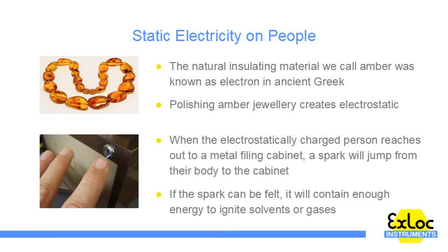If the spark is large enough to be felt or even hurt, it will contain more than enough energy to ignite most solvent or flammable gas atmospheres. Even a tiny spark that may not be felt can ignite the more sensitive, or low minimum ignition energy, vapours.